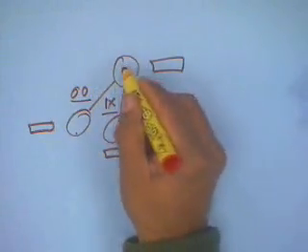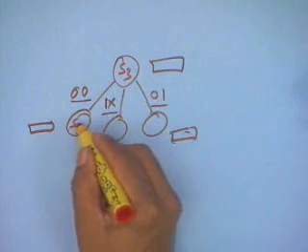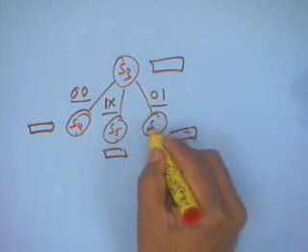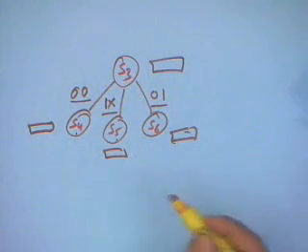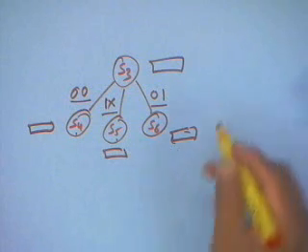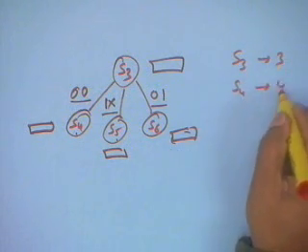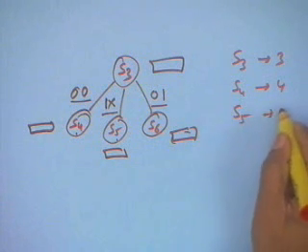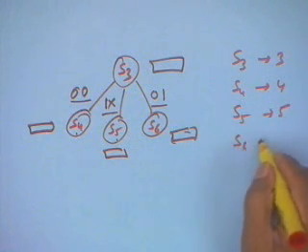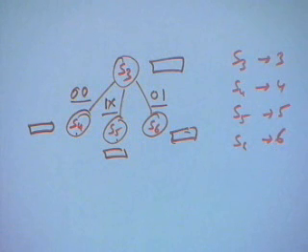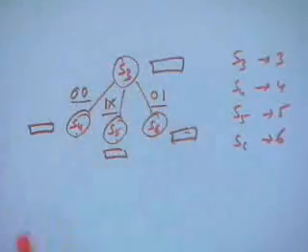So let us say this is some state S3, this is S4, this is S5, this is S6. I map S3 to address 3 of the microprogram, S4 to address 4, S5 to address 5. But in this particular model, I do not permit this direct implementation of such a state machine, because the problem over here is like this.